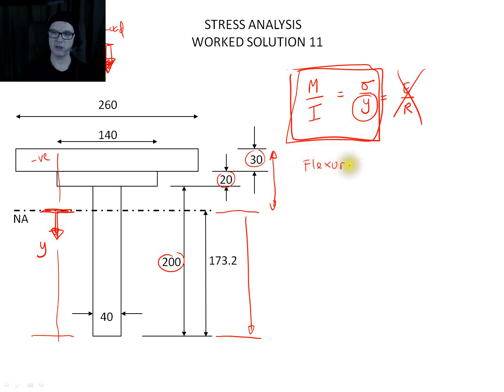So the engineer's bending equations we usually rewrite, because it's the term that we're usually interested in, to something called the flexural equation. And this is the way that we normally would be applying this equation to work out what the stress is. So the M I get from my bending moment diagram. The I I've calculated by using a table and trying to work out the second moment of area, and the y I come back to my geometry and decide what y I'm looking at.